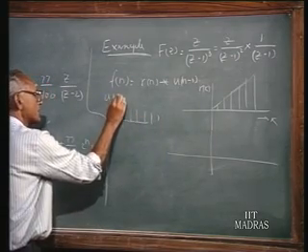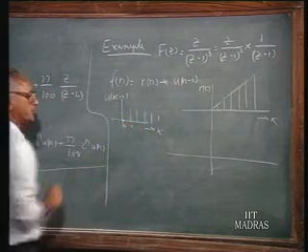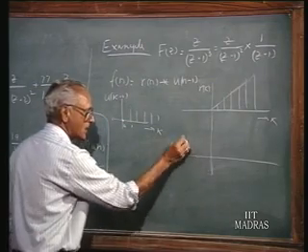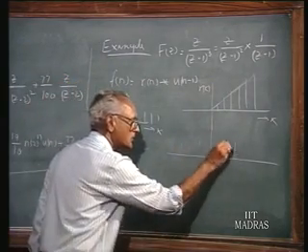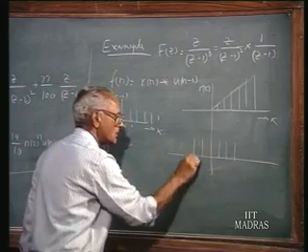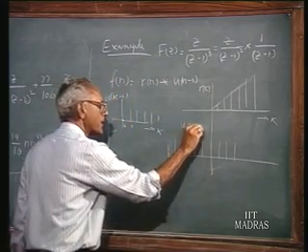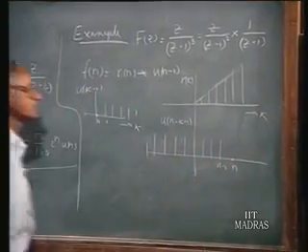With reference to k, this is equal to 1, this is equal to 0. Now you fold it, that means it starts with 0 and comes like this, and you advance it by n units. Therefore, you have this is u of n minus k minus 1, where the nth sample is here, this is n minus 1.